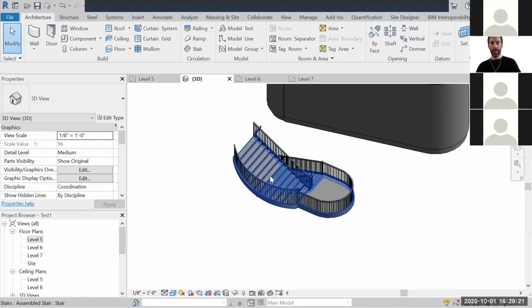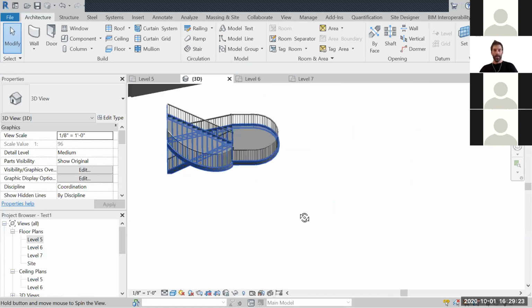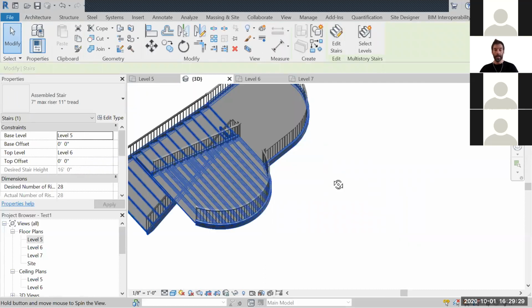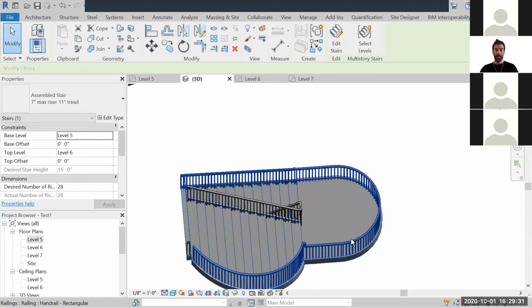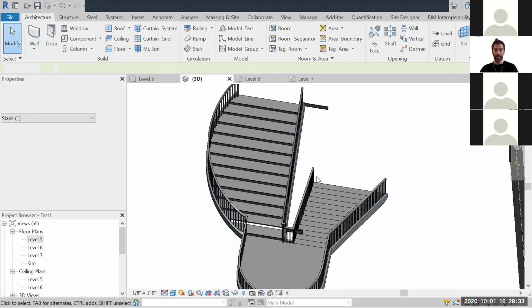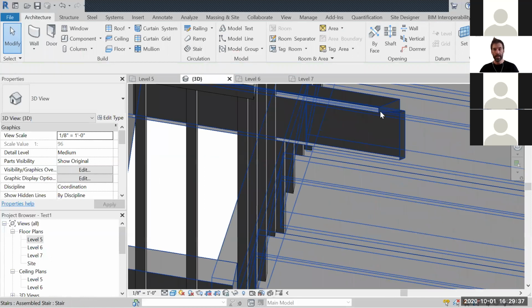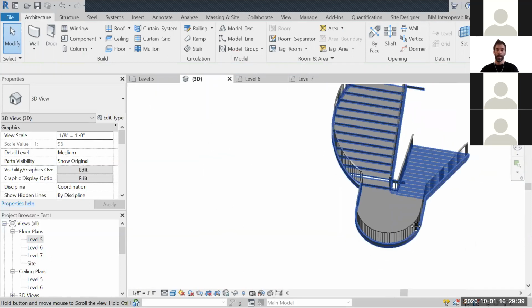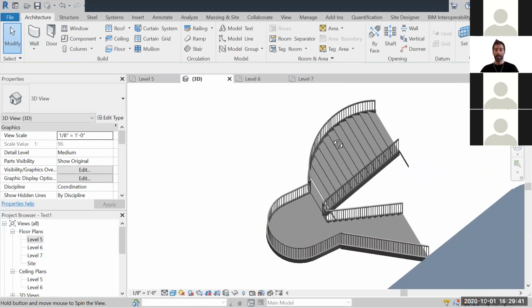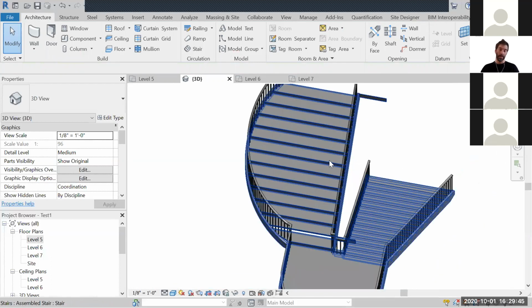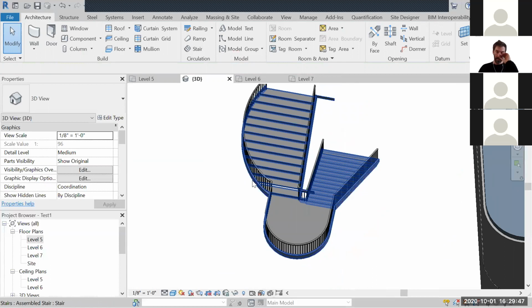By the way, there's another issue. Sometimes orbiting is not orbiting around the objects. Select the object, and then it orbits around that object. It's actually very, very useful and necessary. Notice how we're starting to have some little concerns. That's the Revit world. Complex things give problems. So be careful. And I'm doing not a complex, but a kind of weird thing for Revit standards.